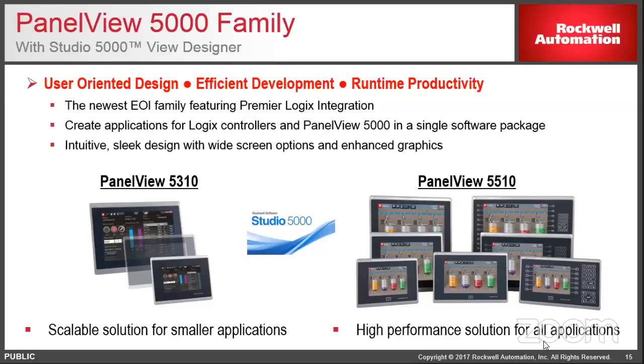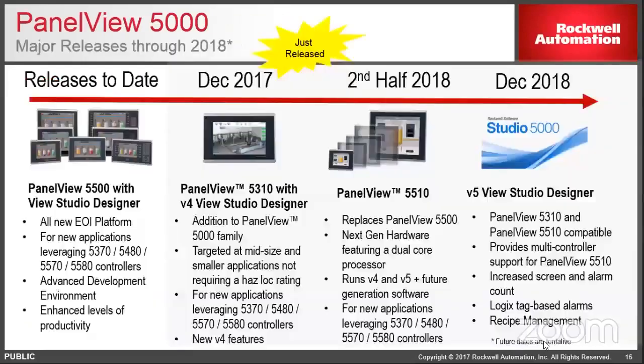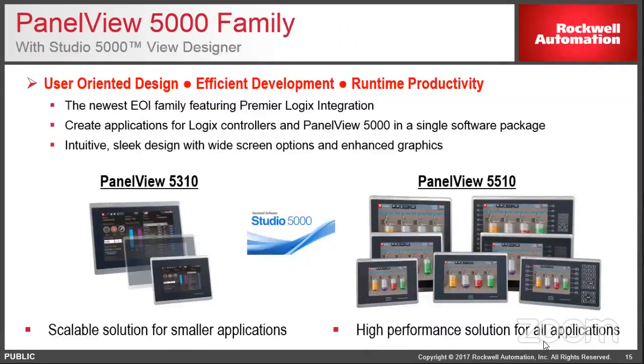We have the two different options there, and everything is programmed in Studio 5000 View Designer. So if you've been playing with or using Studio 5000 V27 and newer, you have View Designer on your system today. And so these are the products you can use that software to program. And one update to it also is the way to update the firmware on these new PanelViews is Control Flash.